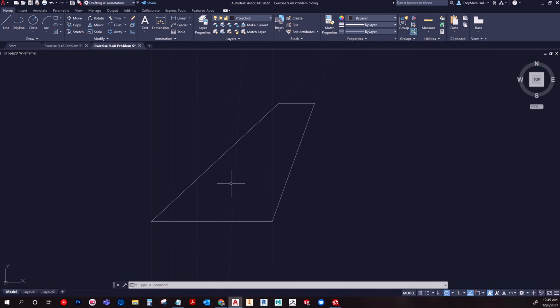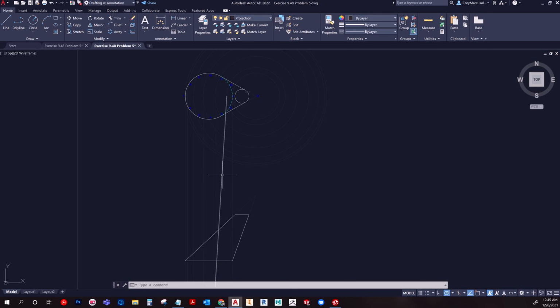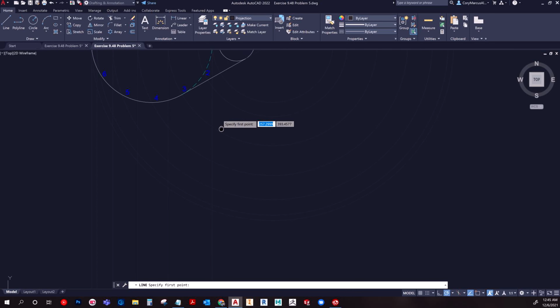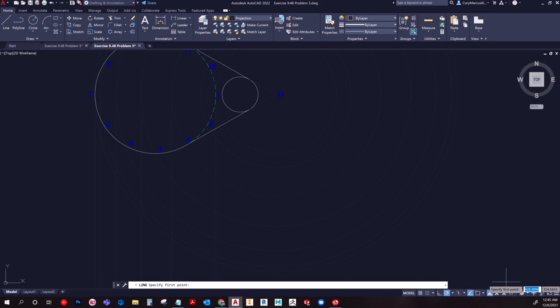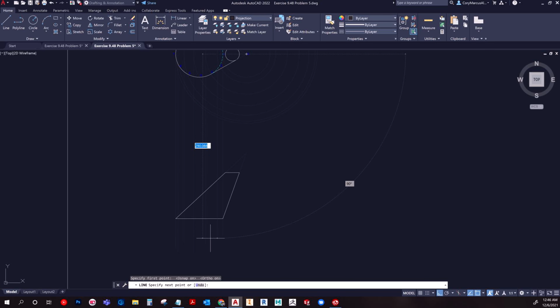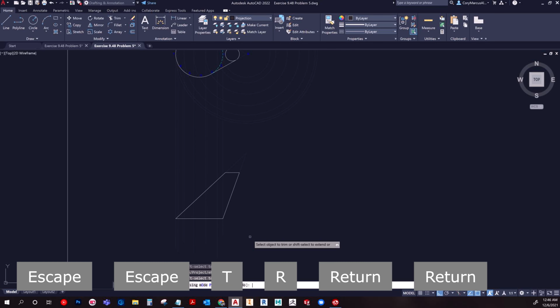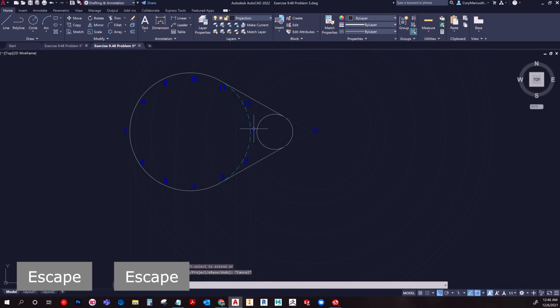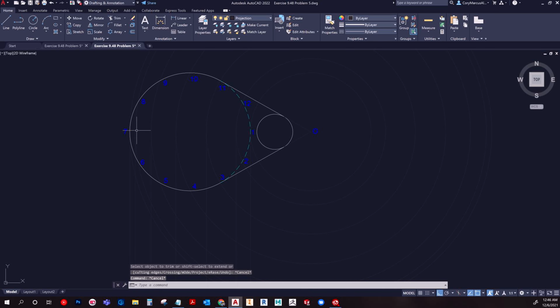So now that we have those, and it looks like I had a line snap off the vertical line path that it should have been. I'm going to put ortho back on and redraw that one. And we'll just trim all these off since we're here. Okay, so make sure we have one for each of these, and we do.